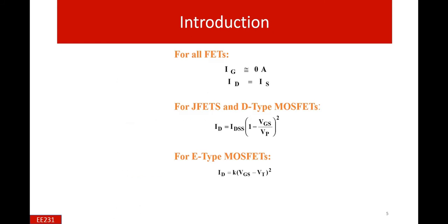The fundamental relations which are still applicable in all types of FETs are that these devices operate when the gate current is 0, and because it is a unipolar device, the current flowing through the channel, the drain current, is equal to the source current.